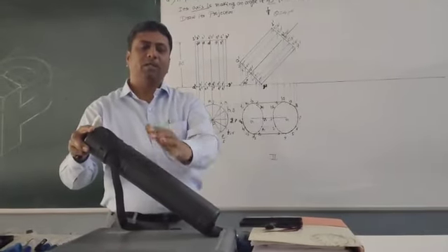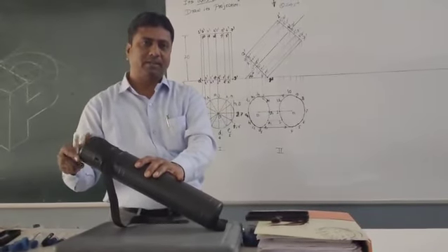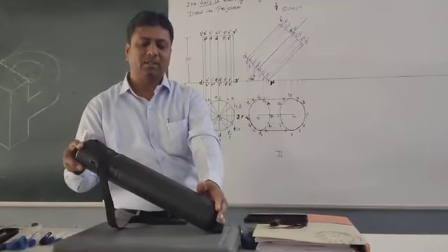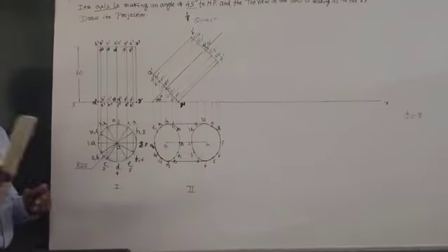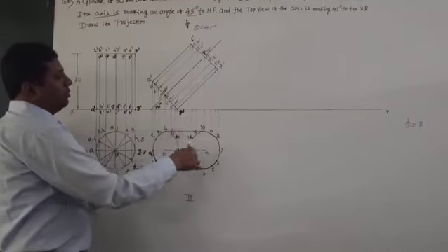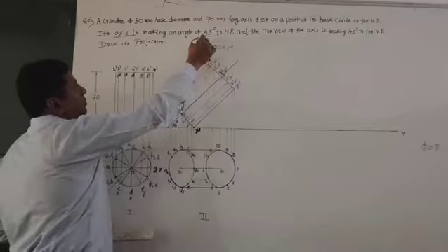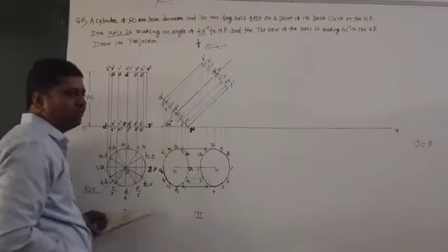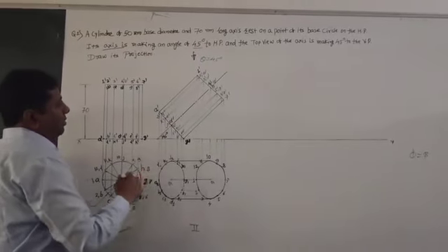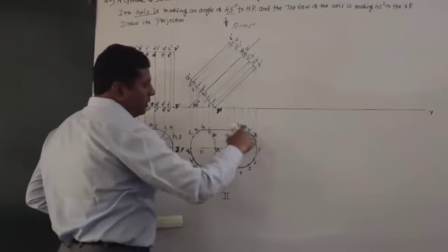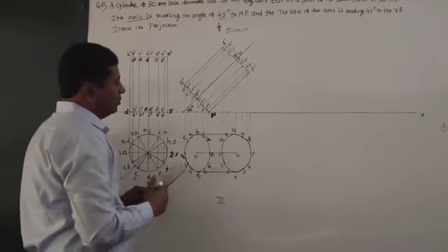Okay, in the front view, but in the top view it is straight away. You will see this base also and this base also. So similarly here, then how to show the continuous and dotted lines, that is the question. For that, what you have to do? Now this arrow you have to bend. You are the observer, you are observing this cylinder. First thing, outer point must be dark. This is the rule.